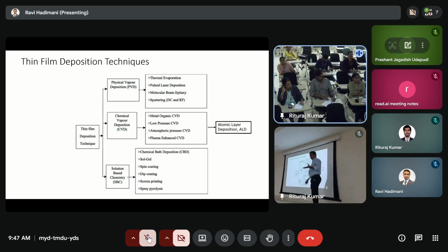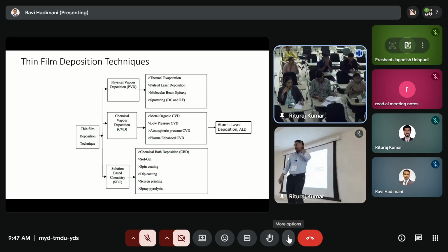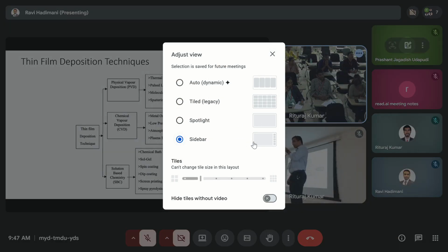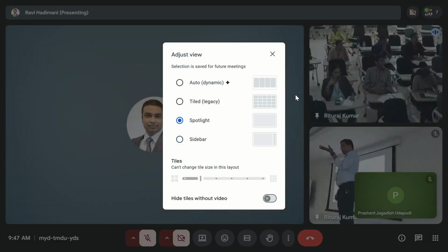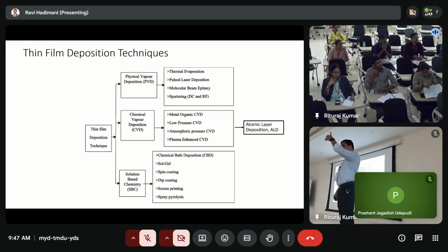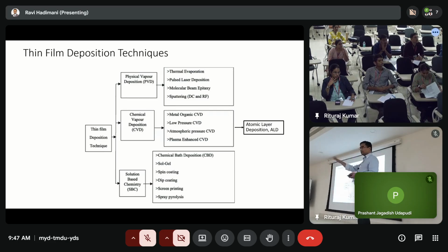There are several ways to prepare thin films. One I talked about yesterday, right, which is spin coating. If you use a high surface finish wafer, like a silicon wafer or glass, and drop any solution and spin it at 10,000 RPM, then you can get 100 nanometers.